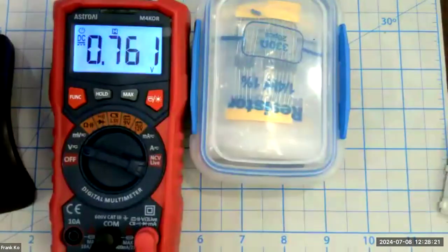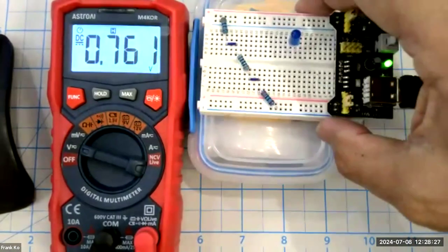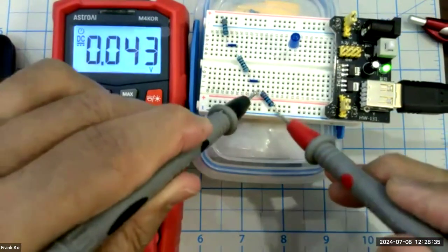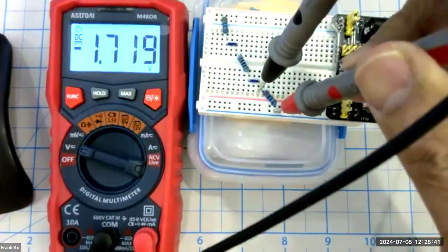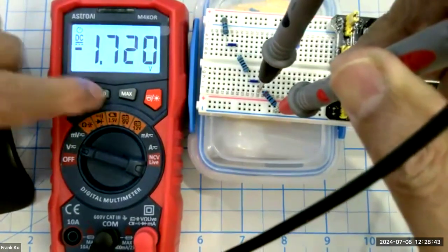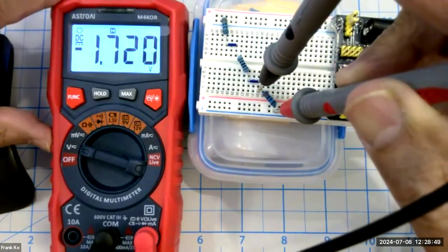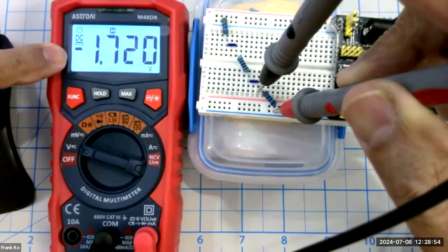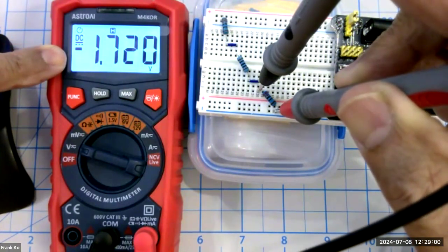All right, last one is to verify that we have the 1.69 volts. So go ahead, pop this guy back, release my hold, get my probes back on. And I'll show you something interesting also. Check this out. We expect something like 1.69 volts, and you go to hook this up, you say, hey, that's not bad, 1.71, hold. But wait a minute. Something's odd about this. Do you see what's odd? Take a look at your multimeter, you see this negative sign in front of your voltage? Say, oh my gosh, how do I get negative voltage?